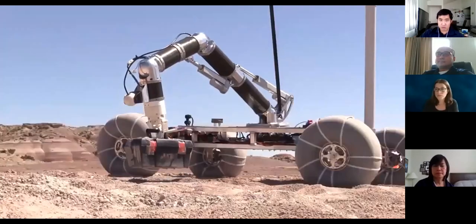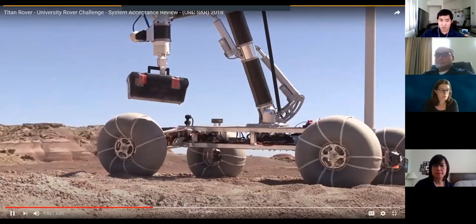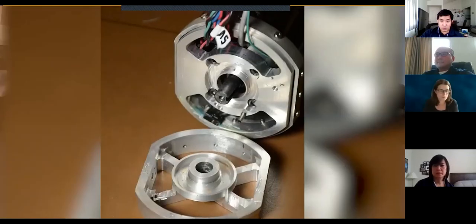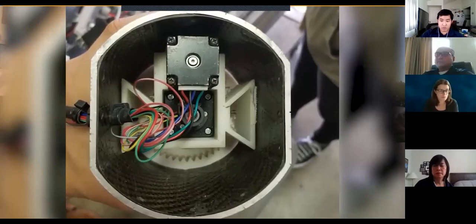The robotic arm is designed for both form and function. It features 5 degrees of freedom and utilizes carbon fiber limbs that act as structural members while acting as an internal channel for all cabling and drive systems.